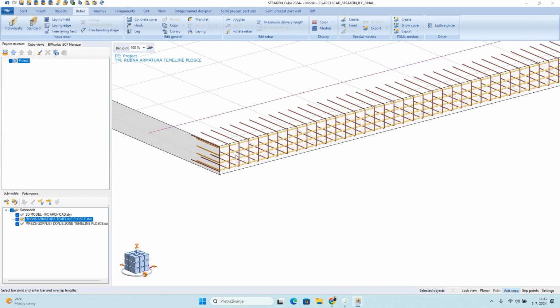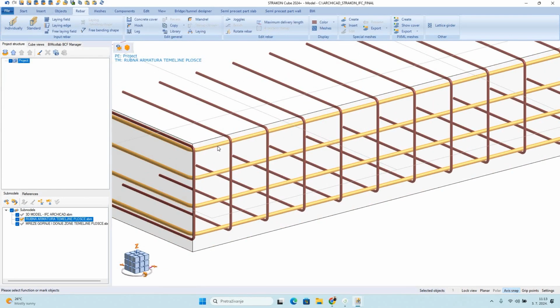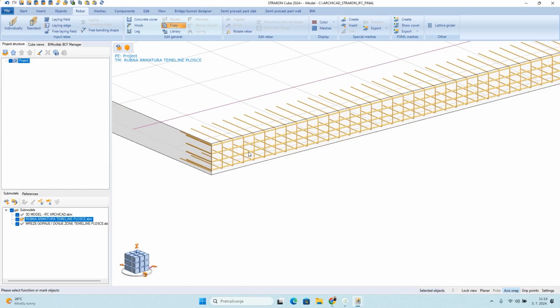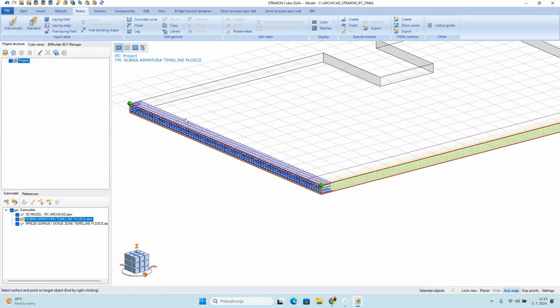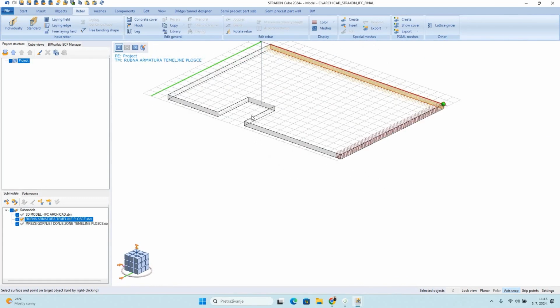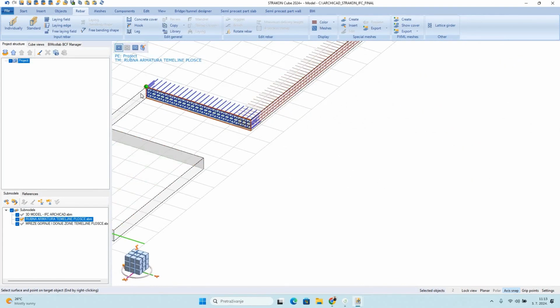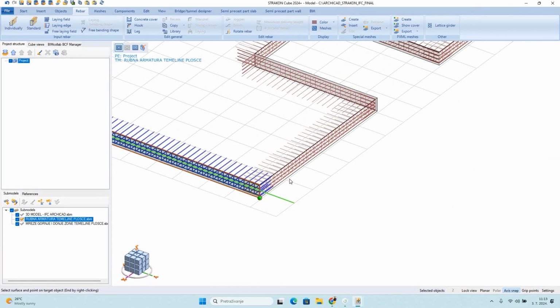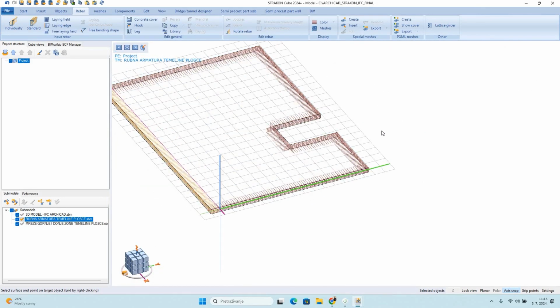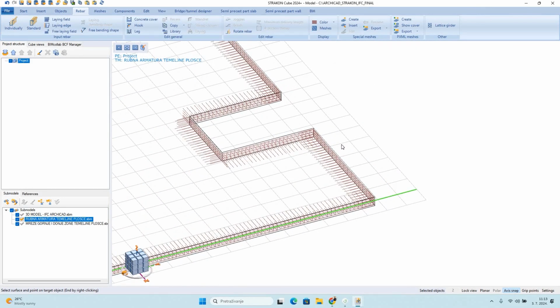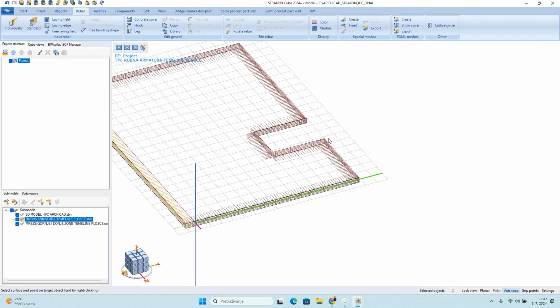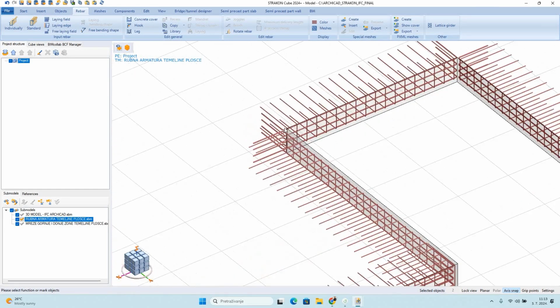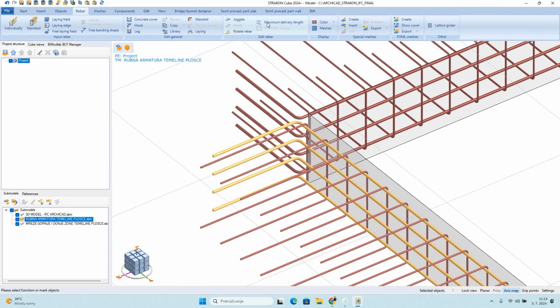After we put overlaps in our wire rebar, I will go to copy the reinforcement to every side, and the only thing we need to fix is the hook, to make it straight on some edges, and we will do that when we copy to all sides. Now I right click and accept the copy command. I finish the copy of this reinforcement, and now I only need to put a straight end on the first and second edge.